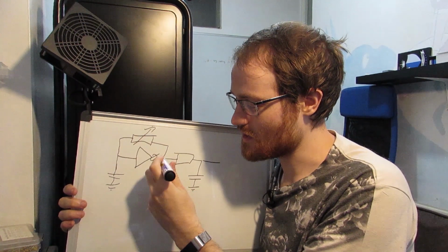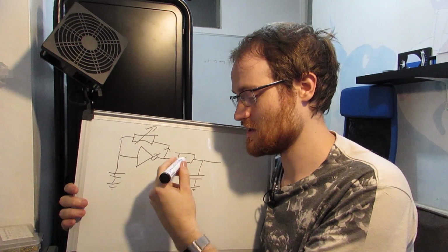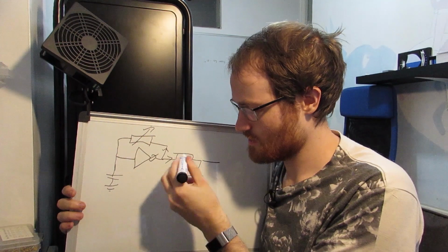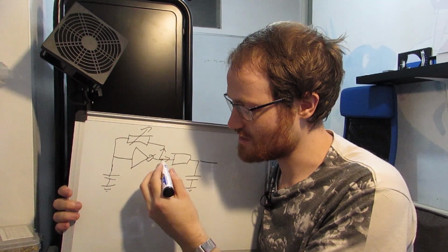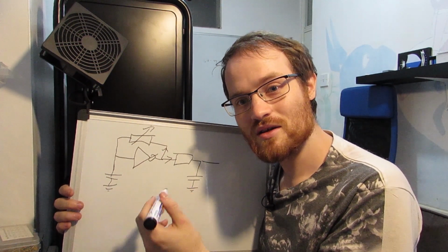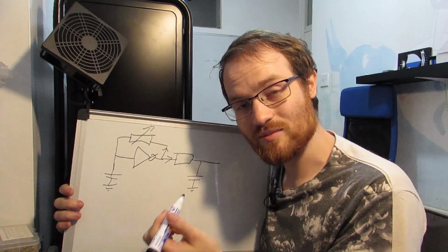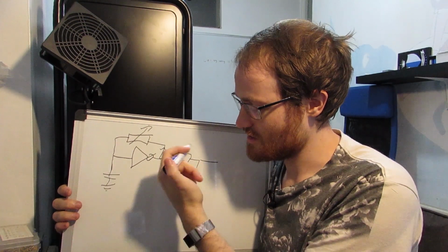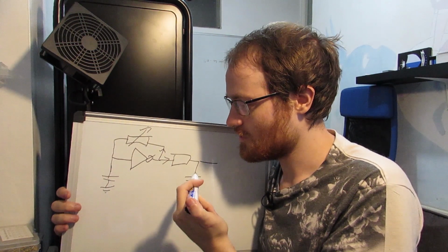Now the current coming out of here is going this way like it was before, but also has to come down this way to power these components here. So as we attach this, it draws a little bit of the current away, so this charges up slightly slower, which is what drops that pitch down. That's a problem. The reason this is happening is that this impedance is too low, so it's drawing too much current.